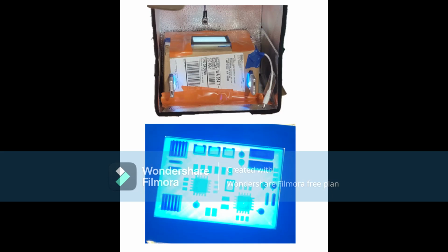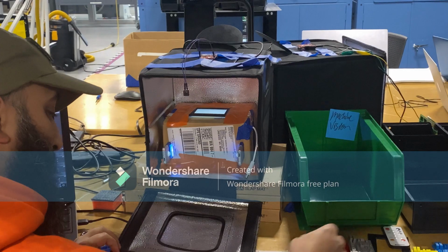Backlight also proved to be an important player in this vision system, with the parts containing just enough transparency and variation in elevation of parts that the tops of the components contrasted the base of the circuit board, allowing the camera to recognize the individual components more successfully, with the addition of backlight in comparison to overhead light.